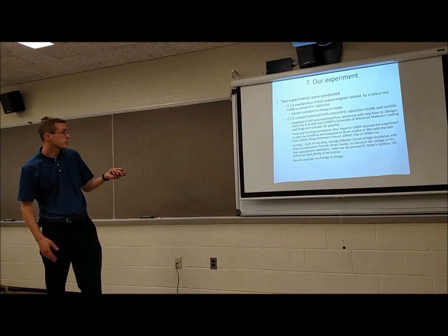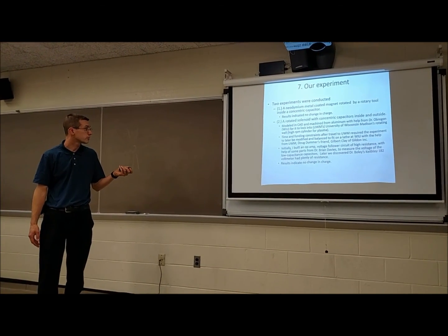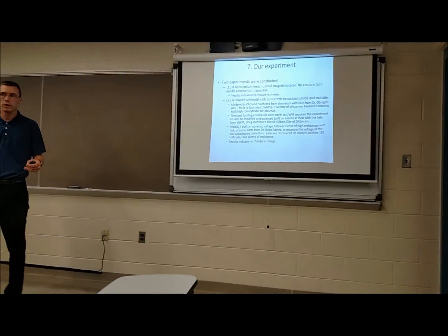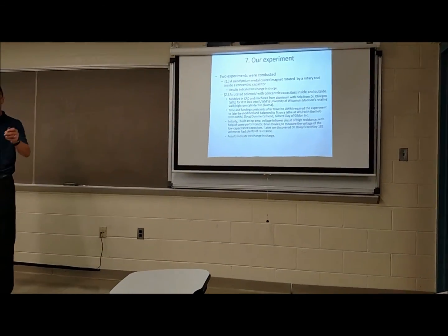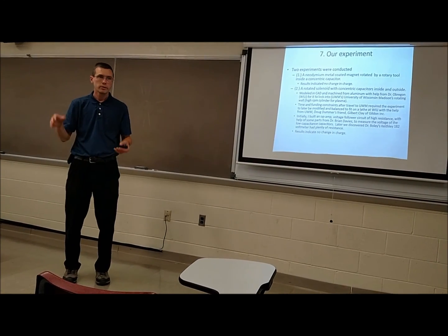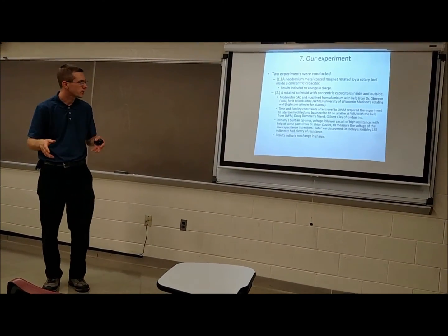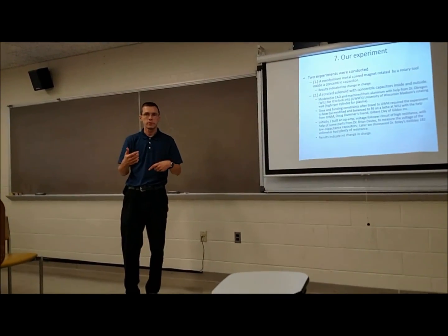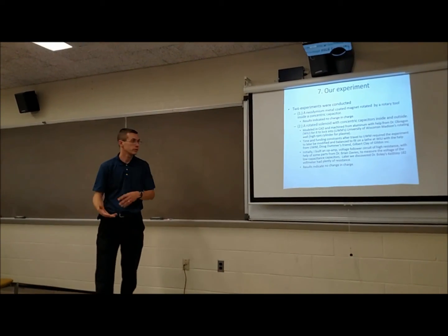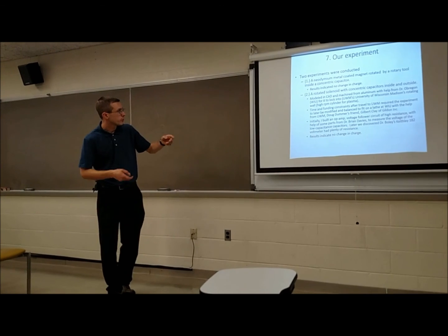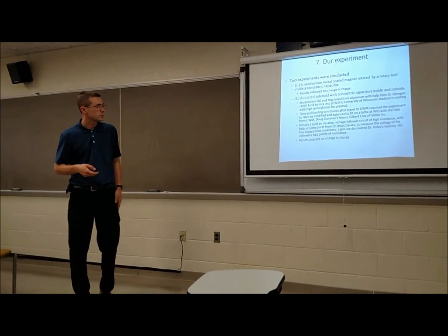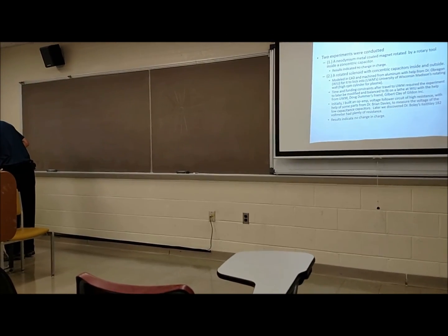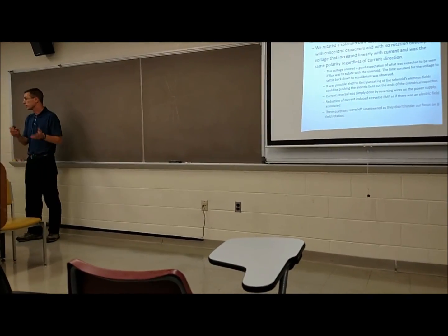Initially, I built an op-amp as a voltage follower for higher resistance, with some parts from Dr. Brian Davies, to measure the voltage of these low-capacitance capacitors. They have these giant rings, which I'll show you. They're made out of aluminum, really low capacitance. They don't hold much charge, so at a lower resistance you'll get charge flowing out of those. You need a very high resistance to keep the charge on the capacitors. Later on, we discovered Dr. Bowley's Keithley 182 had an op-amp built into it, plenty of resistance. Our results indicated no change in charge for the experiment with the rotating solenoid.